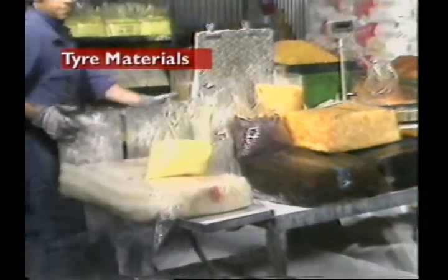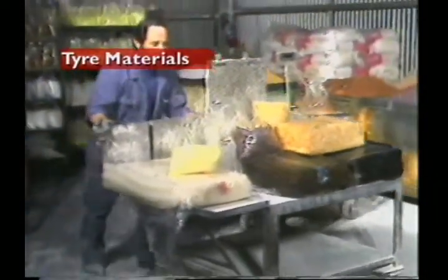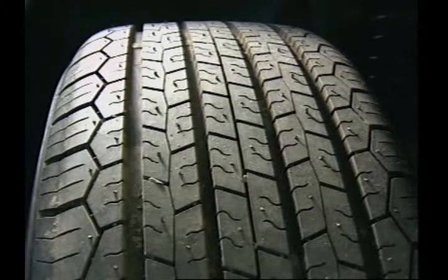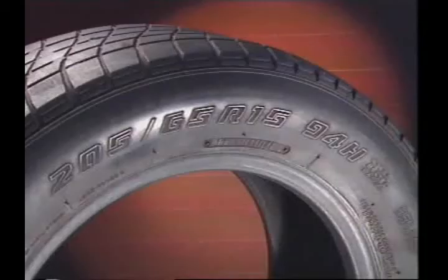This section examines tire materials. Modern tires are made from a range of materials. The rubber is mostly synthetic, with carbon black added to increase strength and toughness. When used in the tread, this combination gives a long life. Natural rubber is weaker than the synthetic version. It's used mainly in sidewalls.